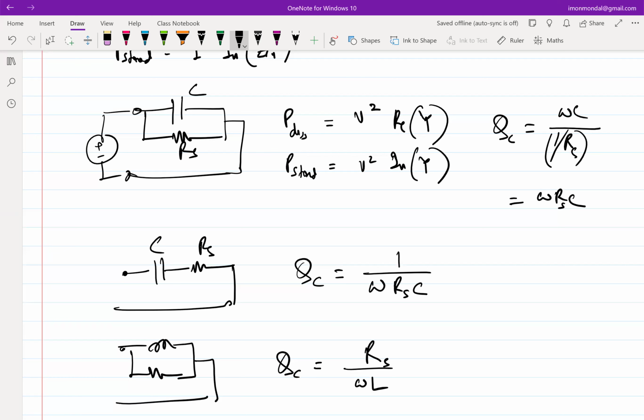Okay, but again, this is a very hand-wavy statement. It's not as if you do not want either. Depending on case-by-case basis, you might see a different usage. But rule of thumb, if you are in the lower gigahertz regime of operation, you use the inductor to only resonate out the imaginary part of the component of your matching network. If you are at very high frequencies, then you use capacitor to resonate out, and step up, step down is done by the inductor, right? Simply because they are more efficient.